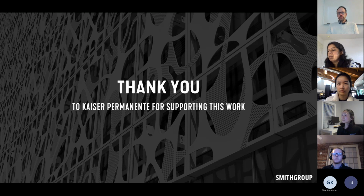That's a good question. I don't know. We can follow up with our contracting team that's working on this particular thread of medical office buildings. I remember the conversation you're talking about: if within the BIM model we could have the zone number that matches the zone number that shows up on the BAS, then when we pull data for zone 1-033, we already know the area and the room types in that zone, and therefore we can do really quick comparisons of the data within the zone.